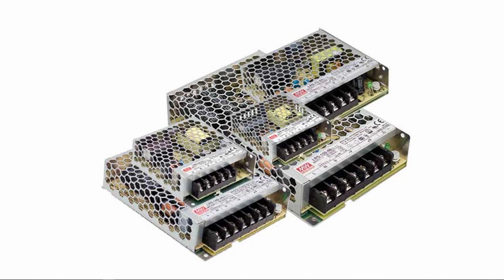Now, I can't really read these. I wasn't planning on reading them. The brand is Meanwell, M-E-A-N-W-E-L-L, very common brand. And if you look close at the terminals, you've got L, N, ground, plus V, and minus V. So it looks like they're giving you one input for line, that would be hot, one for neutral, one for ground, and then you've got two for minus and two for plus. This is just to make it easy for you to distribute.